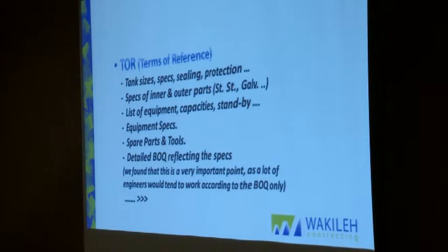We have specified the tank sizes, the specifications of the tank, of the concrete, of the sealing, of the protection, if you need epoxy protection, etc. All these details, they are money, and you really have to specify it. Then we have to talk about the inner and outer parts, whether they are stainless steel, galvanized, or epoxy coated, or painted. That also makes a big variation.